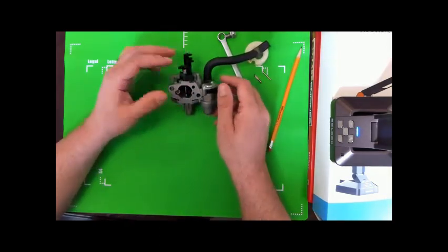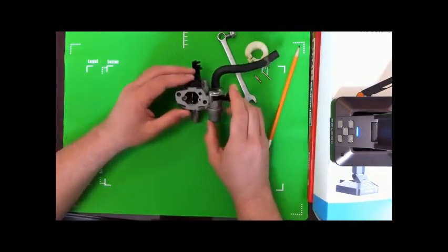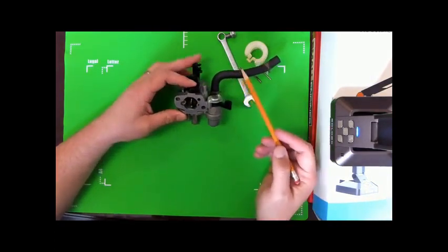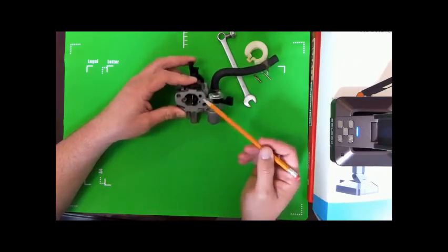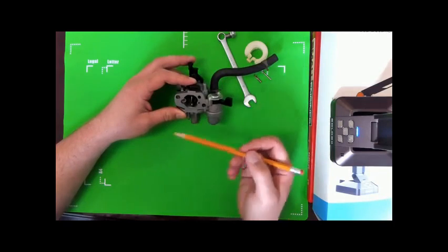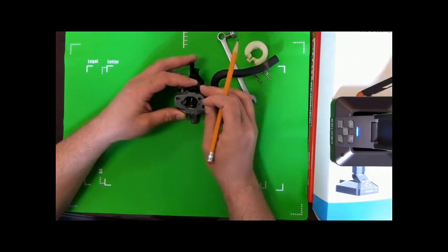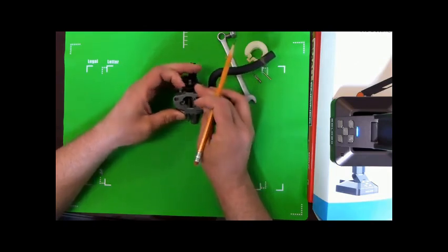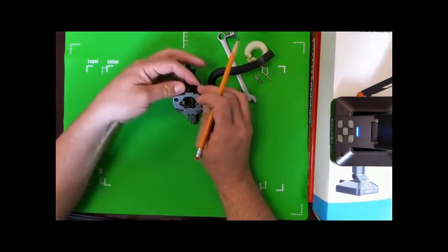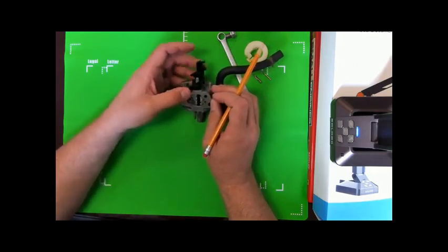If we back up and talk about what a choke is, we typically use it in a small engine to aid in cold starting. Because as we talked about with the fuel systems, the entire purpose of this carburetor is to vaporize the liquid gasoline and mix it with the air coming through to the combustion chamber. When the fuel is cold, like literally cold ambient temperatures, or even if the engine is relatively cold, starting the engine can be very tough.